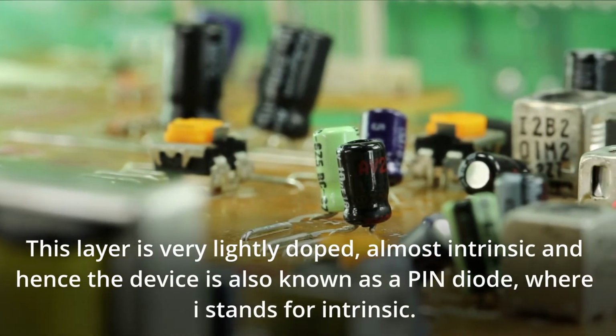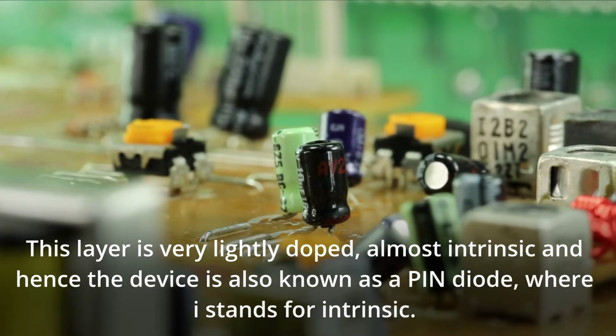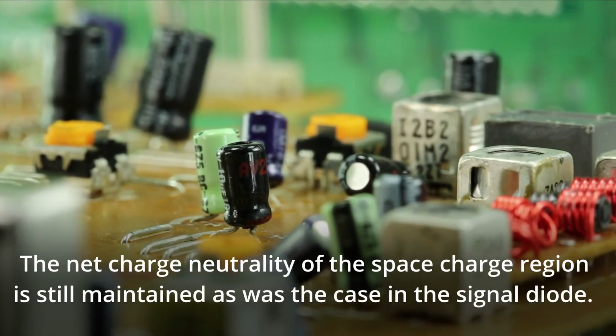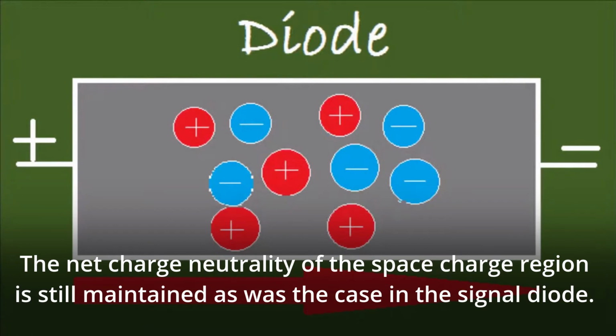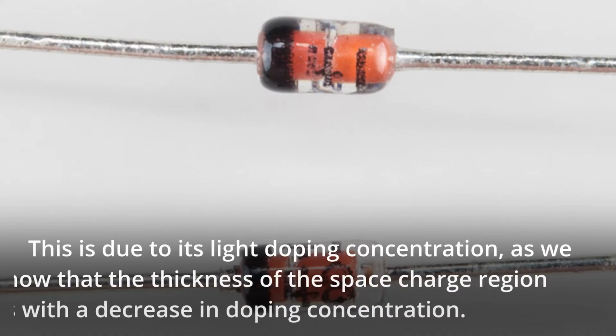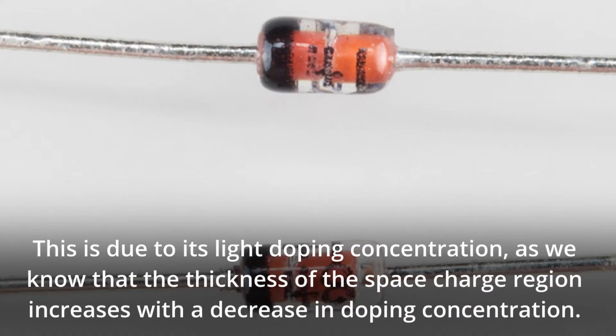This layer is very lightly doped, almost intrinsic, and hence the device is also known as a PIN diode, where I stands for intrinsic. The net charge neutrality of the space charge region is still maintained as was the case in the signal diode. But the thickness of the space charge region is quite high and deeply penetrates the N- region. This is due to its light doping concentration, as we know that the thickness of the space charge region increases with a decrease in doping concentration.